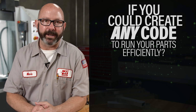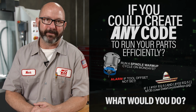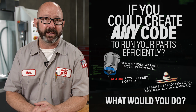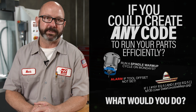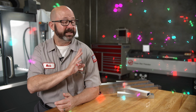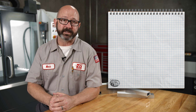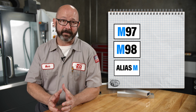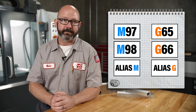Sky's the limit. If you could create any code that you wanted to run your parts more efficiently, what would you do? Let us know in the comments. Now, chances are it is possible to do what you're thinking, but it's going to involve some custom macros and subprograms. Now, I think that these 6 codes form the backbone of advanced programming on Haas machines: M97, M98, Alias M, G65, G66, and Alias G.